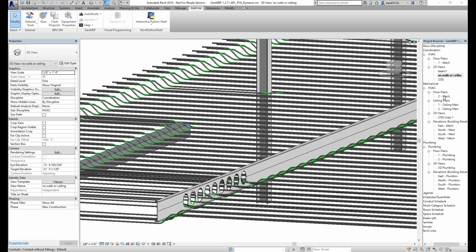Okay, so Marcus Armenta asked, can this logic be used for cable runs as long as I have start and end points? It can be used for cable runs. Cable runs are nearly identical to conduit, except they can go at any angle and they have a defined bend radius. So as long as we can define a bend radius and do a cable run, those are also within what we can do.